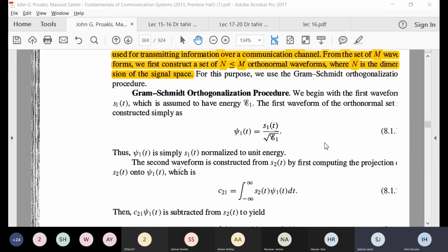Sir, you take the magnitude of x of t, square it, and integrate from minus infinity to infinity. Yes, yes, yes. I have told you many times. I know you have also studied this in your previous courses, but we also repeated this in chapter 2. First of all, x(t) is the instantaneous value. Take its square, and this becomes instantaneous power. Then you integrate x square t over its full time, from minus infinity to infinity dt of x square t. That will give you energy.